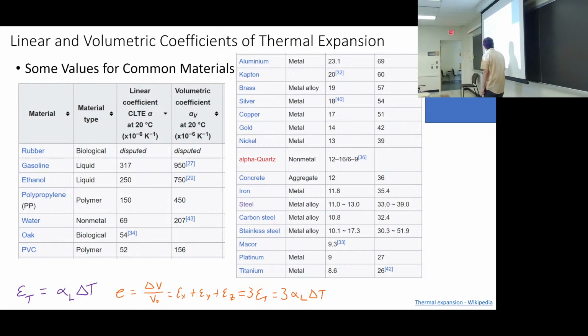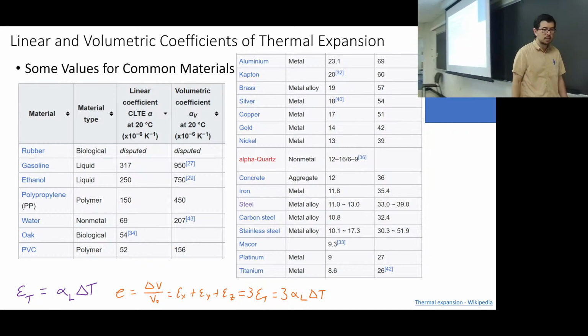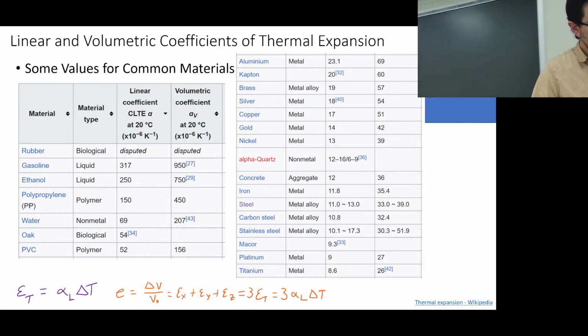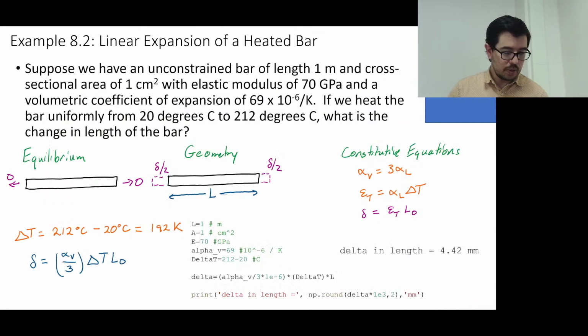What am I trying to say here? The units are important. The reason it's dimensionless in the numerator is because we're talking about strain. It's alpha times delta T. I need something to knock out the temperature, and that's what the denominator of the units for the coefficient of thermal expansion does. So that's just relating these two to each other as we said before.